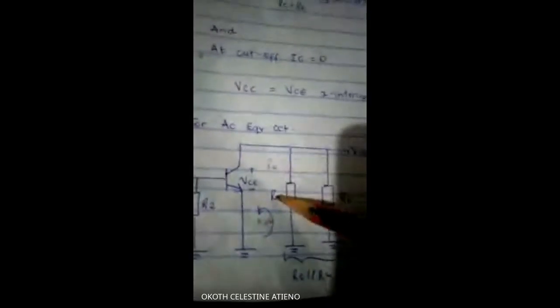First one, in this loop there is a KVL, just looking at this particular section. Here we see the voltage small vce plus ic RC is equal to 0, because the sum of voltages in a closed loop gives us 0.